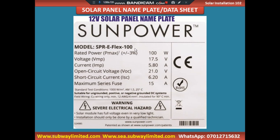This means if you expose this solar panel to the sun or under standard test conditions, as we already said, 1000 W/m², AM 1.5, 25 degrees Celsius, which is the condition this panel was subjected to, you might have a value 3% higher or 3% lower than 100 watts.